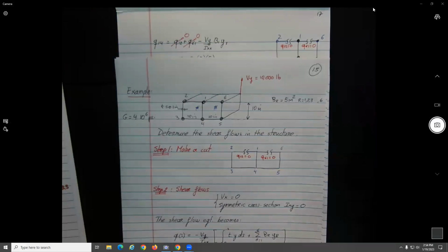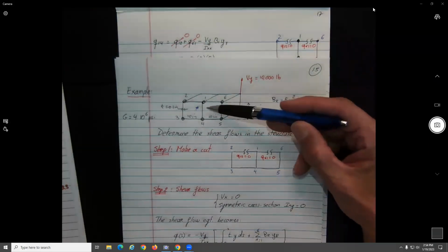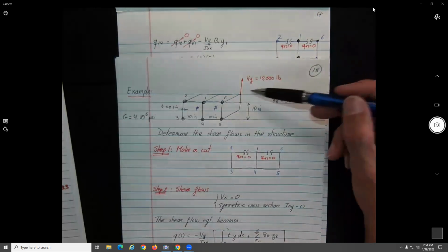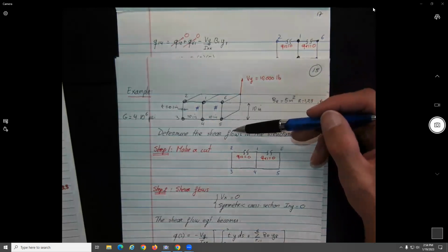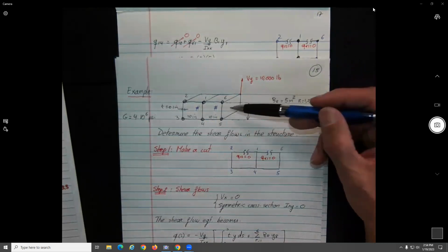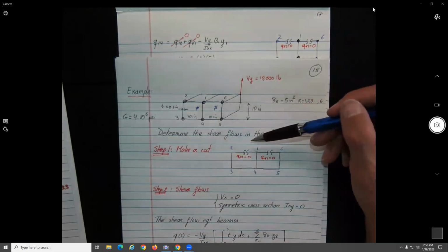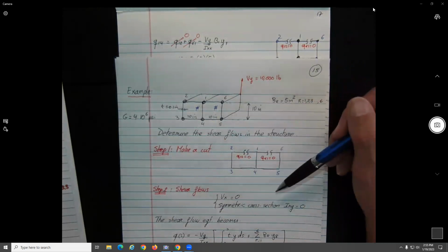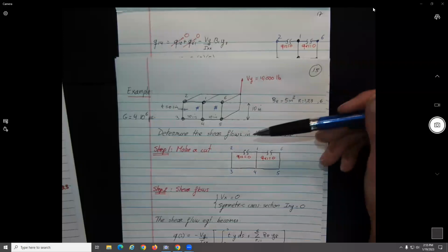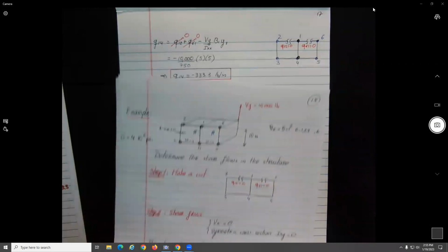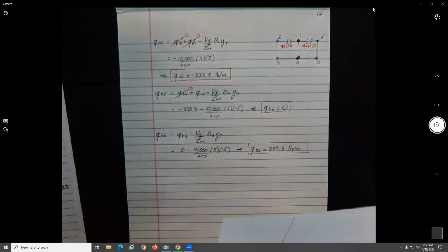Okay, if we make the assumption as we did in the previous section, that only those three members will be carrying the load, what will be the load? It will be 10,000 divided by 3, which is 3,333. If we calculate that per unit length, what is the length of this one here? 10. We divide 3,333.3 by 10. What do we get? 333.3, no? Yeah, so you see, just by logic you can calculate what is happening. But if you want details, you have all this stuff.